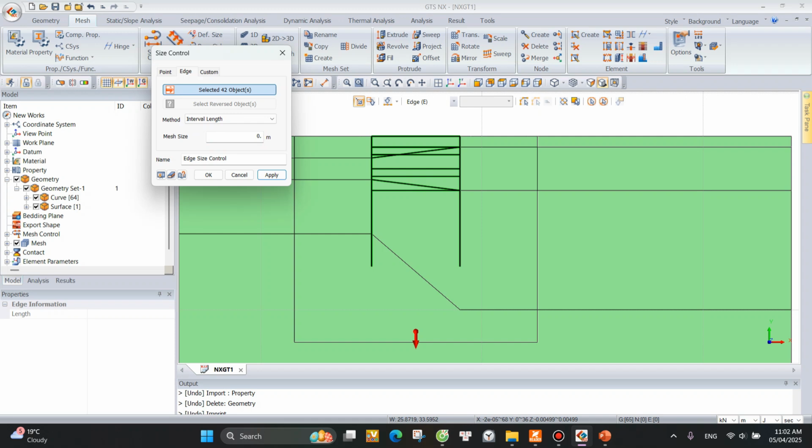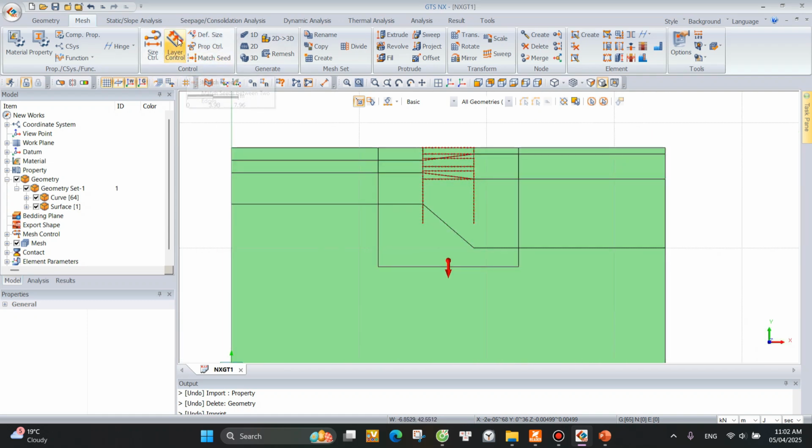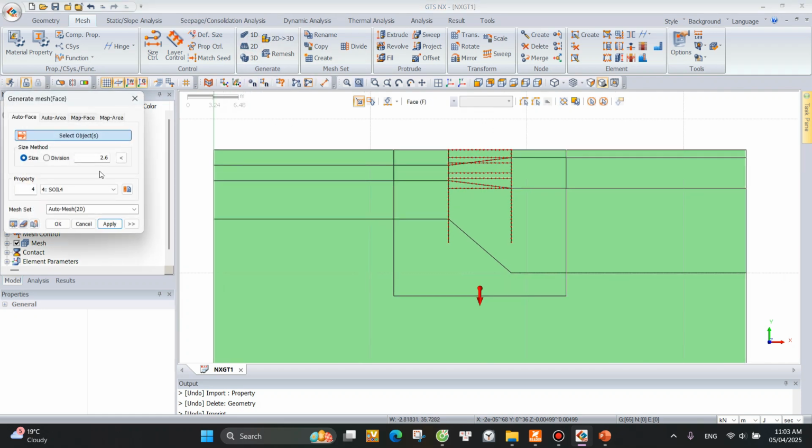So I have 0.5 method for each point along each length we choose, and the distance is 0.5. As you can see here, the distance is 0.5 now. And you can go to the mesh control by create, generate mesh. So now you have different areas as you created last time by the imprint. Now the mesh you control with two methods from the menu.